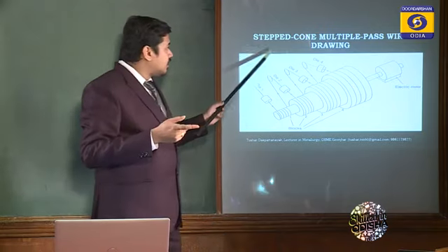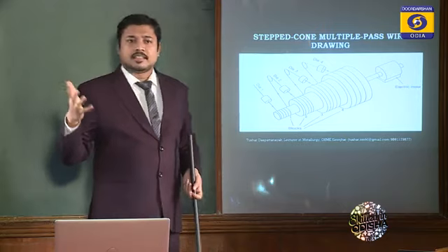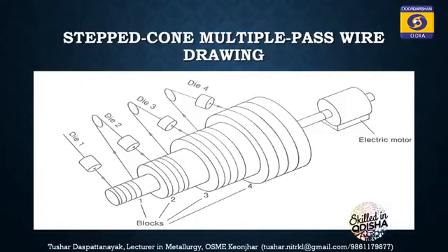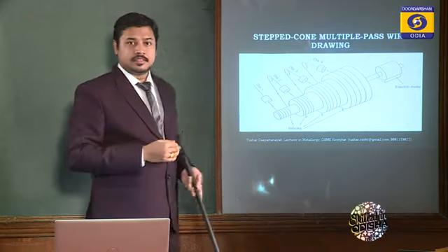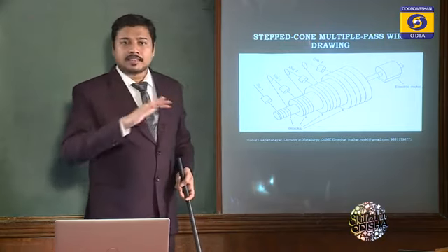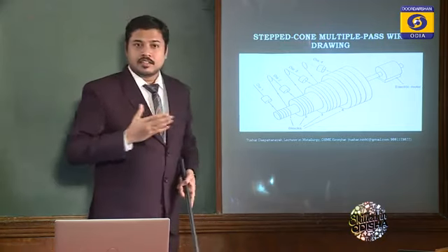There's a question that always comes in the exam. Why is stepped cone multiple pass wire drawing more economical than normal draw bench wire drawing? This is the reason. I'm saving space, I'm saving energy.